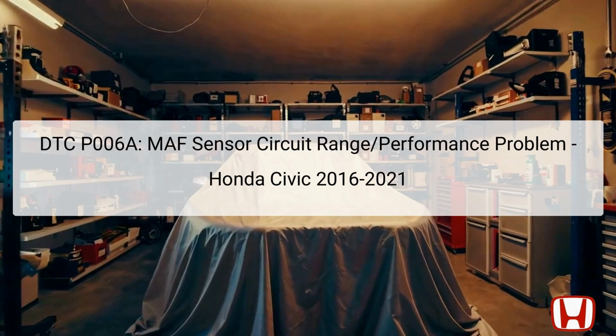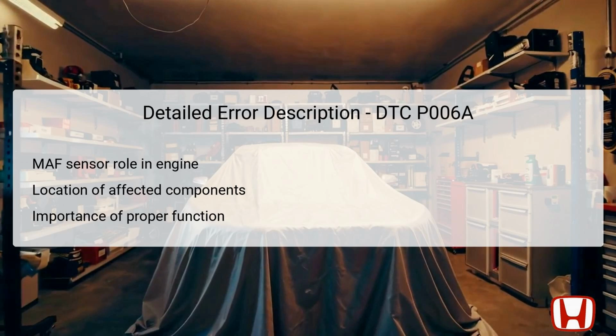into more detailed diagnostics. The MAF sensor, positioned between the air cleaner and throttle body, measures the volume of air entering the engine. Its role is critical because it informs the engine control module on how much fuel to inject, impacting engine performance and emissions. If the MAF sensor has a performance issue, it may not read the air intake accurately, leading to incorrect fuel